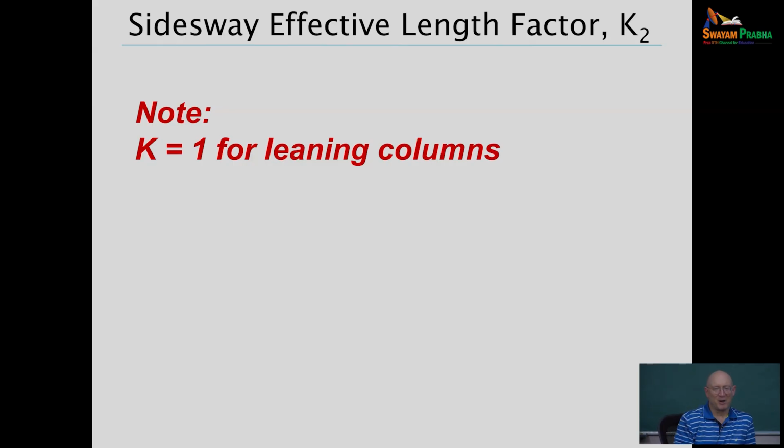Then comes the thing that's really confusing with buckling-based solutions with side sway. You say, but I've got a very light, very flexible spring connection. That connection represented by a spring at top and bottom to a column over there on the right. Now you get into something that in the literature is referred to as the effective length factor paradox, where it's really not so appropriate to use this really large K factor for something like that because it's not really helping the story.